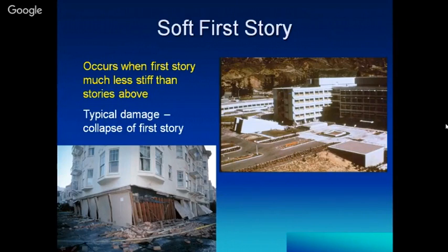Soft first story failures. Now we come slowly onto the real structural failures of earthquakes. What are soft first story failures? Most of the time you might have seen that in our multi-story buildings we have parking lots, and in our parking lots we don't provide the brick infill as a structural element, which, if provided, would contribute to the stiffness of that particular floor. We don't provide that brick infill structurally connected to the columns and beams in the ground floor parking slots. Due to that, we have an immediate story stiffness difference as compared to the stories above.